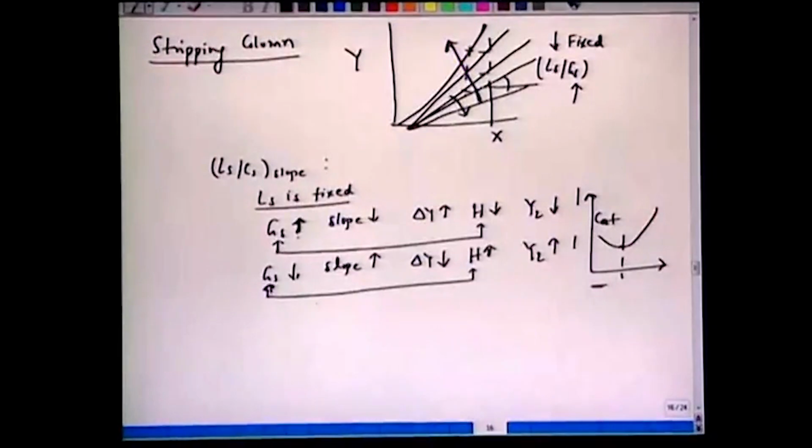Okay, so in this situation, when we approach the equilibrium curve, there is a risk of the operating line making a tangent with the equilibrium curve, where we have what we call the pinch.